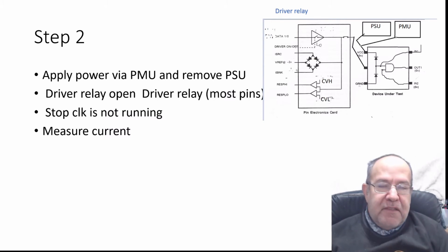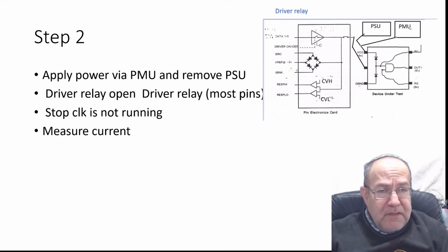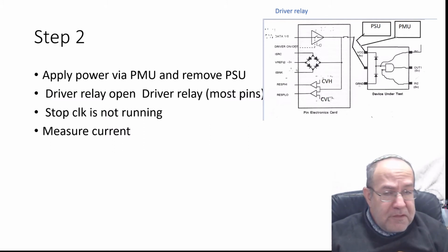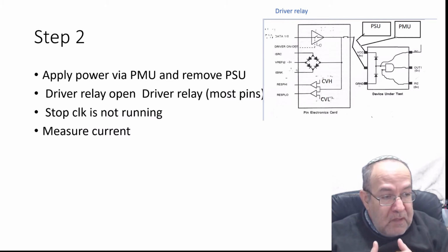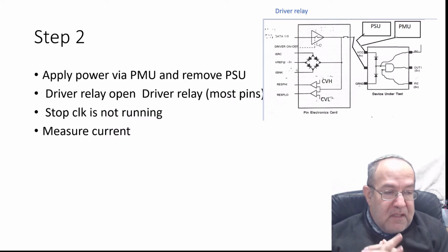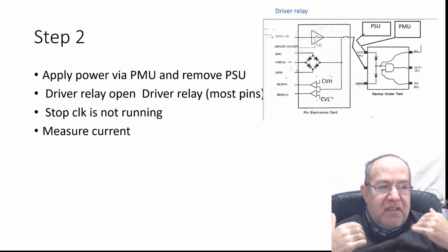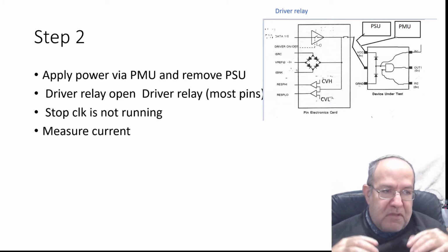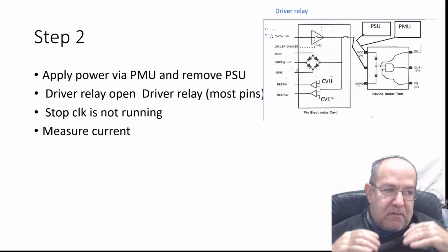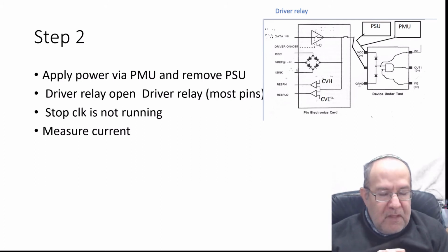At this point in time, I institute a current measurement, and I measure the current, which is a steady state current of the device at a known state with most of its inputs open, tri-stated in the air.